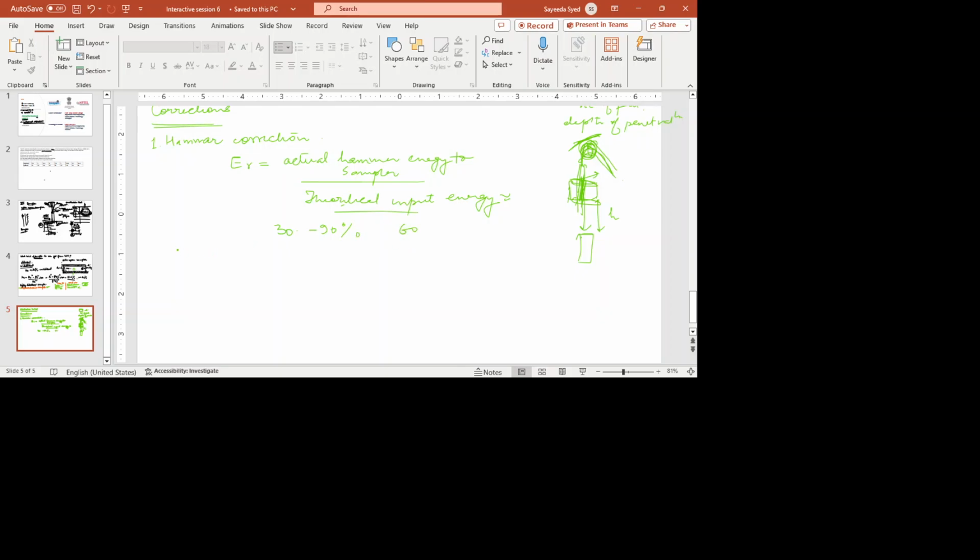And the SPT value corrected, like if we calculate the penetration for last 300 mm of the sampler, the number of blows if we calculate, and it gives us an uncorrected value n. And then when we correct it for hammer, we usually write it as n60, because usually we take the hammer efficiency as 60, but in our question it has been given as 80. So instead of correcting with 60%, we will correct with 80%. Okay.